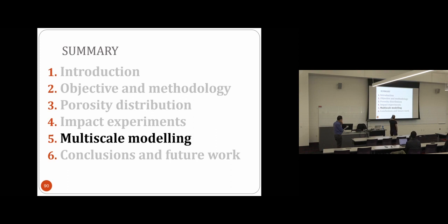The local stress in the spall, yes, because we have the signal, and with that you can correlate the free surface velocity with the stress within the target. This is classic. In some of the experiments with the Hopkinson bar, yes, because we are using DIC analysis. I have some slides there. We are checking with DIC how the buildup of plastic deformation and the buildup of strain rate occur, trying to correlate this with the evolution of the porosity.